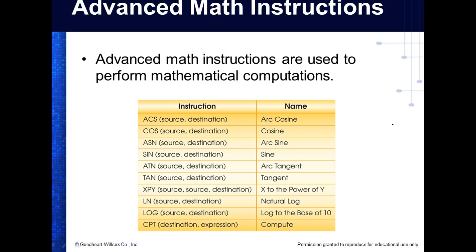You understand? In the old days of PLCs, we would literally get enough rungs that it would mess up, because it wasn't scanning inputs at that time. So what we had to do was duplicate the rung. If we had a very high priority input, we would duplicate the rung, and that way it would scan it multiple times in the scan. Now they finally use something called interrupts, and hopefully we'll get in time for that, where you can literally cause the program sequence to change, so you can set up high priority stuff.